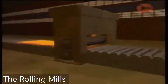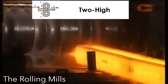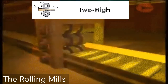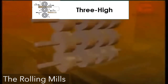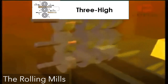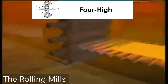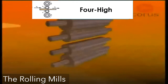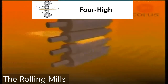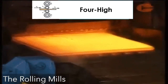Rolling equipment is massive and expensive. The basic configuration is the 2-high, where two opposing rolls are used for longer products like sections. For light sections and bars, the 3-high, where work passes through the rolls in both directions. And the 4-high has two work rolls supported by backing rolls, with the smaller rolls giving a greater accuracy for rolling flat products such as plates.